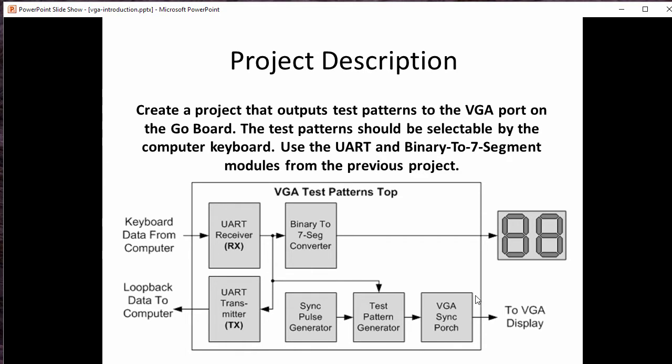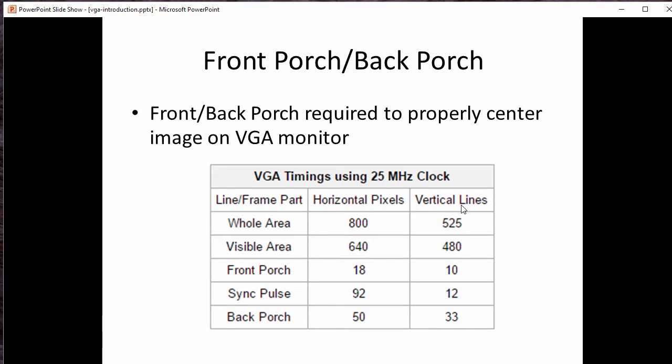And the last piece of code here is this VGA sync porch, which is going to actually modify the horizontal and vertical syncs to add in the front and the back porch. And those timings come from this here.